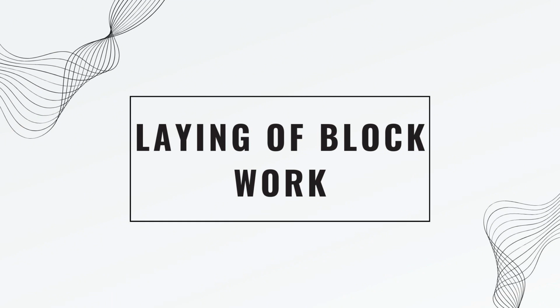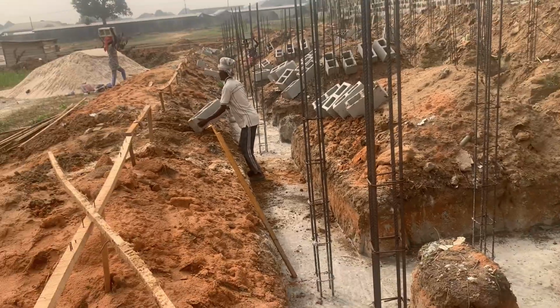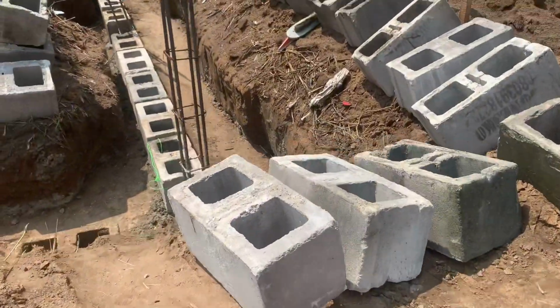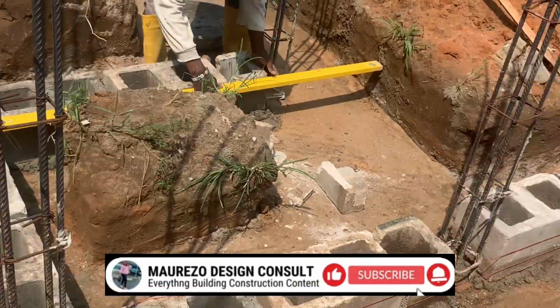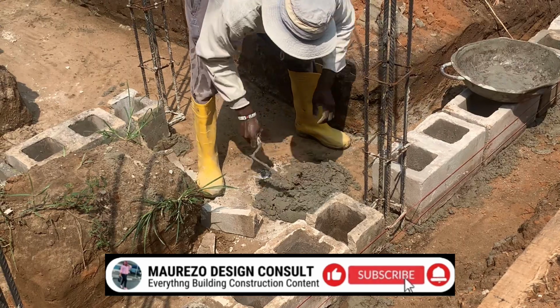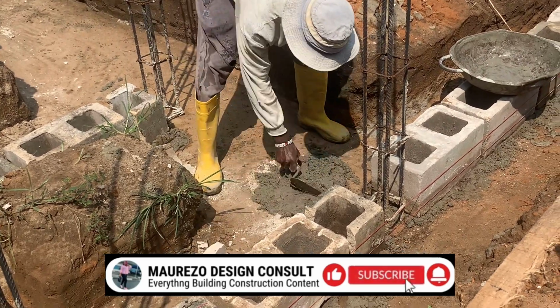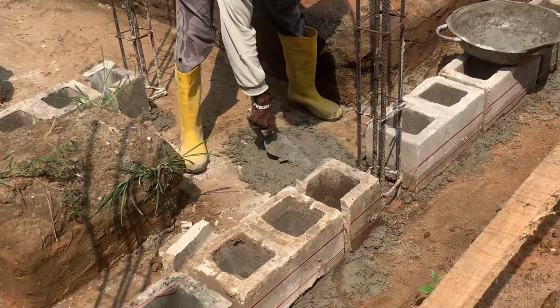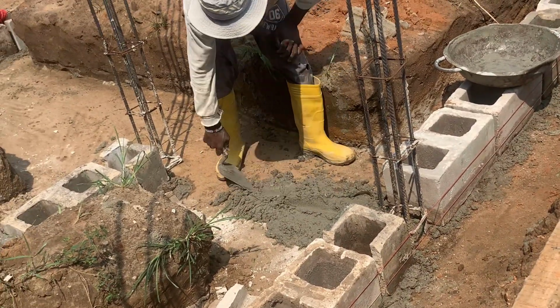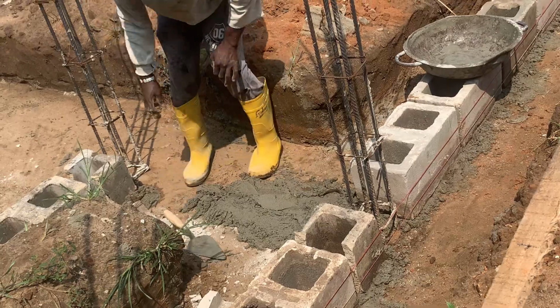Now, the next we are going to be talking about is laying of blockwork to the DPC. It is a very important stage, and of course, care should be taken to ensure all work done at this stage meets the design. Okay. Now, the mix ratio of the mortar can be taken to be 1:4. Okay, but you can make references to the structural design to get your exact ratio.